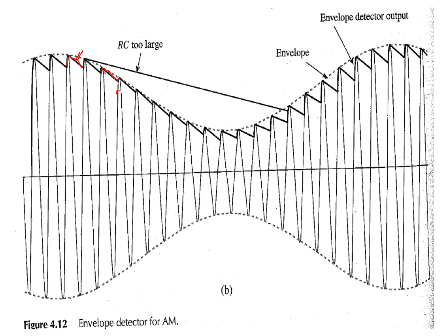the envelope looks like this. Again you go like this, again like this, and again like this. This envelope is not exactly a replica of the message signal. That's why we have to choose the capacitor value, RS and RL resistances, satisfying the condition that the charging of the capacitor takes less time compared to the discharging of the capacitor.